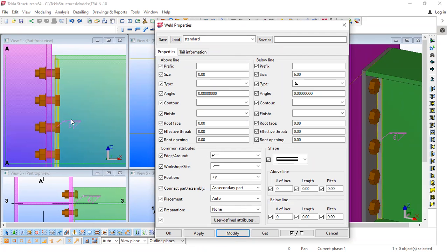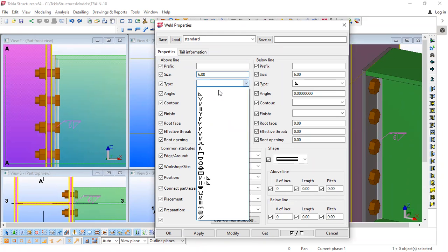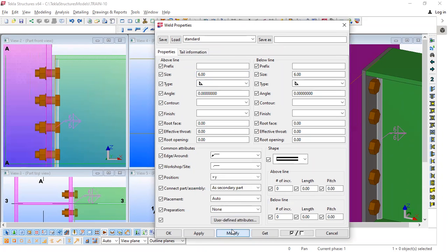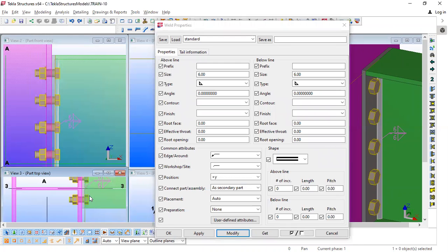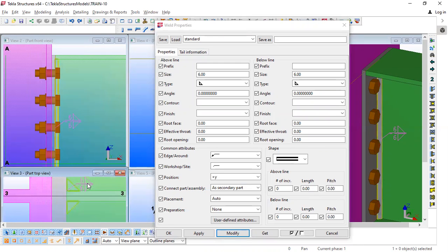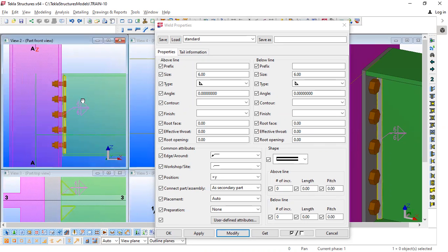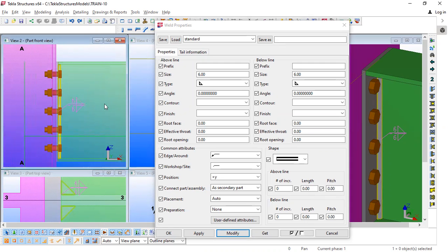And whenever we are changing it to normal weld, you can see that weld is now displayed here. So I can add a weld here. You can say near side, far side. So both the sides, if you zoom here, you can see the weld is applied on both sides. Okay. So on both sides, we can see that triangles are there now. So that means that weld is applied on both sides, right? So that's how we add this welding, right?